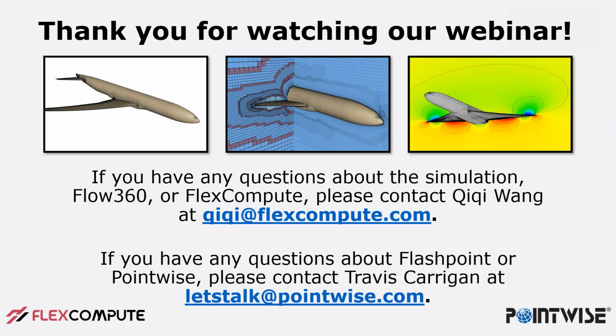All right, Chi-Chi or Fei-Lin, are there any specific mesh requirements for Flow 360? The mesh requirements are pretty much the same as the mesh requirements for Fun3D. So we accept unstructured meshes with tetrahedral, prisms, pyramids, and hexes. Okay, so that's the type of cells we accept.